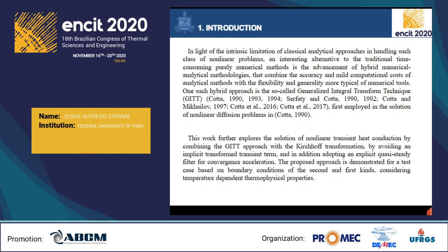In terms of GITT methodology, it has been demonstrated that the combination of the integral transform approach with the Kirchhoff transformation can offer improved convergence behavior, since the new diffusion term is exactly integral transformable and the temperature dependence of the thermal diffusivity is much less pronounced than for the conductivity and capacitance independently.